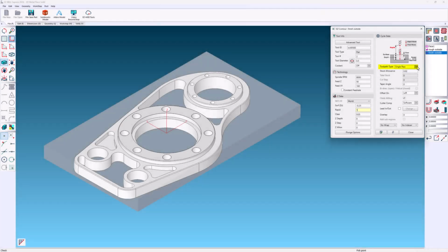Toolpath like single pass is used for those semi-finish or cleanup passes. Multi-pass is one that behaves as a roughing operation with an offset to your profile. You add a total stock for the amount of material you wish to remove and a cut step for the approach. Z-Connect is used for those open profiles. Once you reach one end of the path, EasyCam feeds in a Z based on the value in Z step. This action continues until full depth is reached.